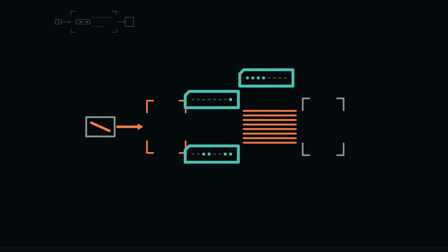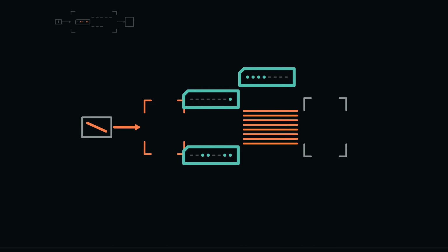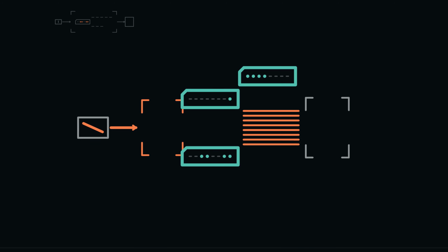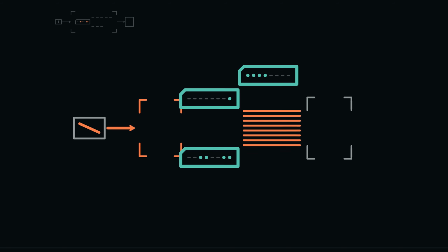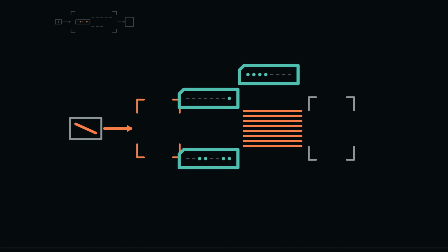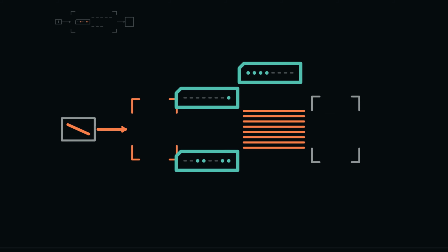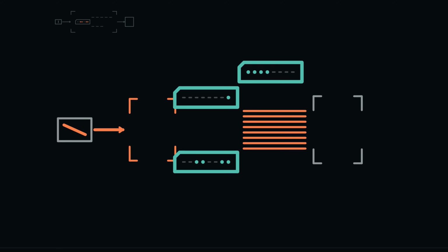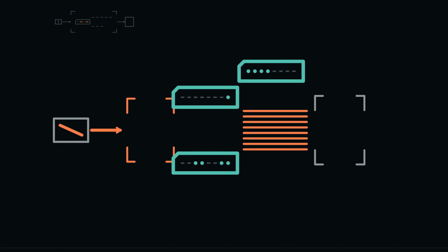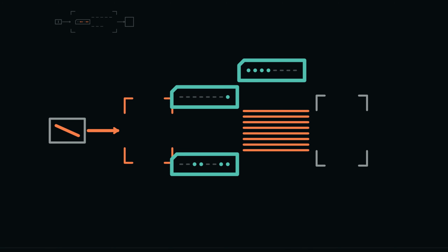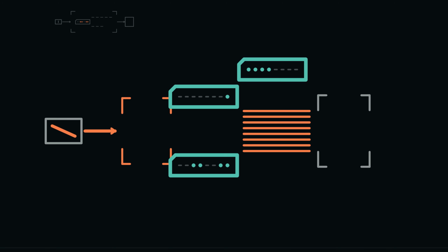Reading keyboard status returns 1 when the input queue contains at least 1 byte and 0 when it is empty. It does not remove the waiting byte. This separation lets a program ask whether a later data read is safe. Writing to the status address is illegal and false. The register is not a little memory cell that happens to sit near a keyboard drawing. It is a defined observation of adapter state with a restricted direction.